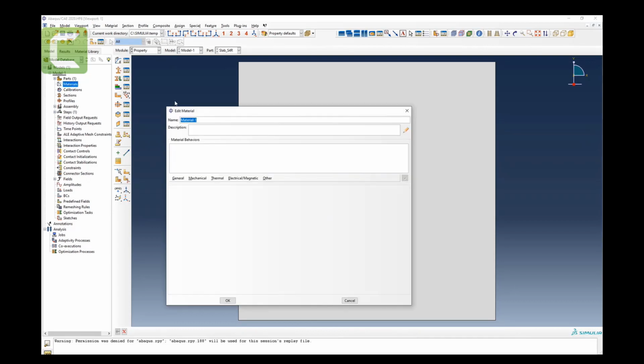So let's click on materials, and let's put steel, it is a steel plate. Again, these names, you can put any names. Your answer will not be affected by what names you put in. You can put material one, or material dash steel. Again, it does not like it if you put a space. The space, they don't like it. What you need to do is put an underscore or a dash.